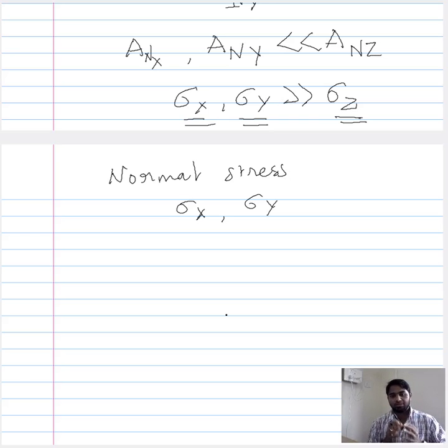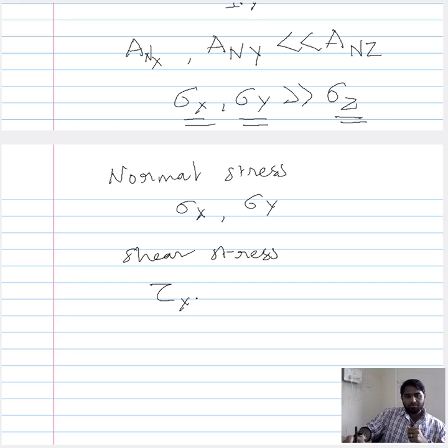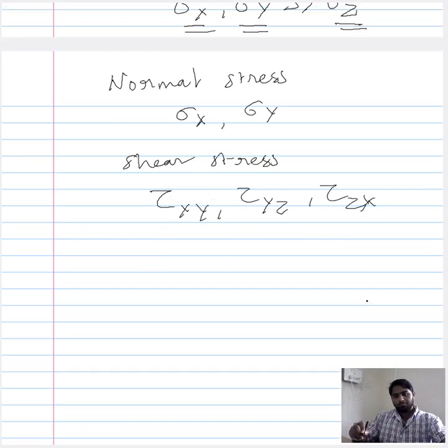So let us see if we can make a similar simplification for the tangential or shear stresses. We write the shear stresses in this manner. We saw that we need 3 independent shear stresses to describe the mechanical condition experienced by a 3-dimensional material on which a triaxial load is applied.